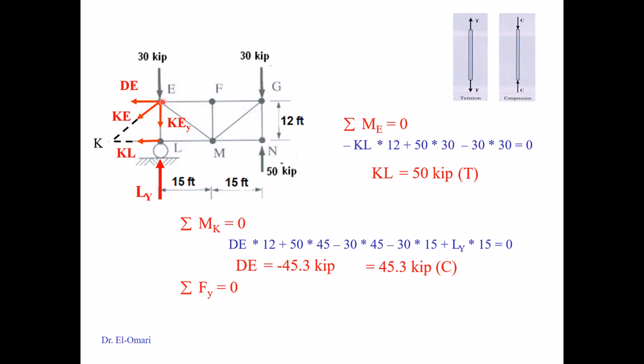So if you look at this triangle, 12 and 15, then I can find the hypotenuse with a calculation of the Pythagorean theorem that gives you that this distance is 19.21. So I could then write the equation, which means that I use the 12 over 19.21 for the vertical component.